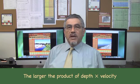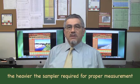The stream flow depth and velocity and the available facilities at the sampling site determine the choice of sampler. Stream depth determines whether hand-operated samplers or cable-suspended samplers should be used. Flow depths over 15 feet require the use of point-integrating samplers to avoid overfilling of the sampler bottle. The larger the product of depth times velocity, the heavier the sampler required for proper measurement.